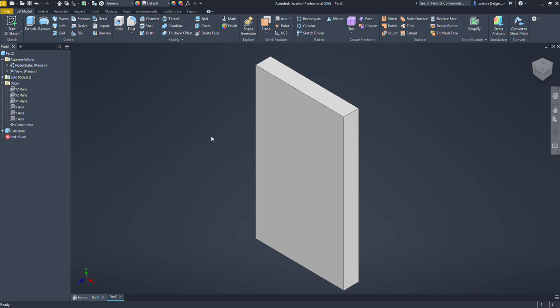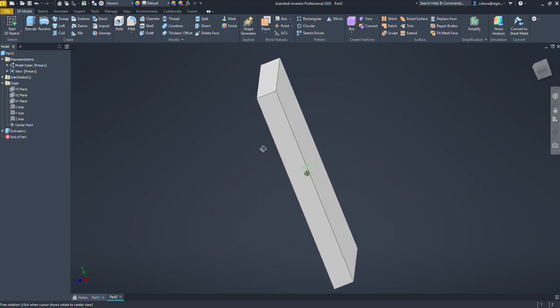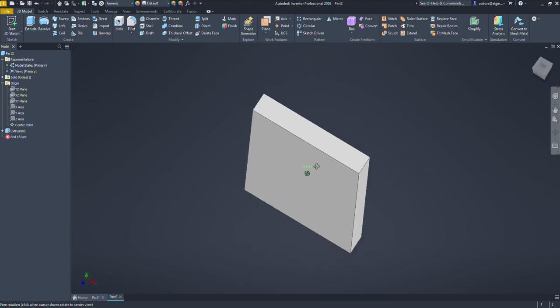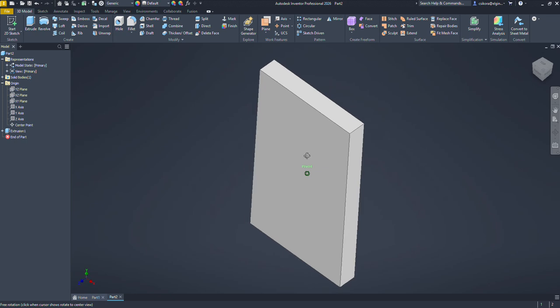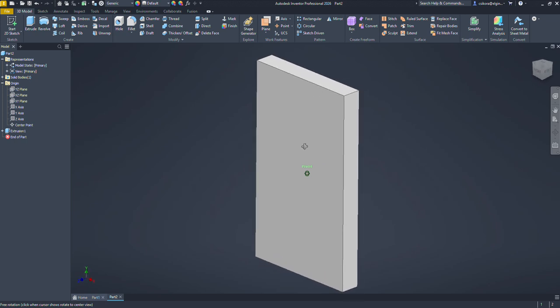Now, you probably want to learn how to manipulate it, i.e. how to rotate it dynamically and things like that. Well, here's how. Hold your shift key down and get your pointer in the center of the screen. Depress your wheel as if it's actually a button instead of scrolling. Like actually push it down and hold it. That's the wheel on your mouse. Now move your mouse left, right, up, and down. You'll see it pivots dynamically. You could release both buttons.